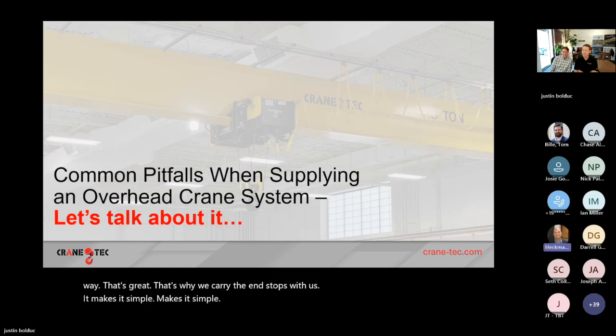Tom Carney has another question here. The EOR, engineer of record, is specifying the crane loading, rail method of attachment, tieback method, Gantrix tiebacks? But the method of support, brackets, separate crane columns, stepped crane columns, is dictated by the building manufacturer typically. I would agree with that. And that's a great point about the Gantrix tiebacks. When you do a comparison from one scope to the next, those aren't always being offered up. So absolutely something to clarify.